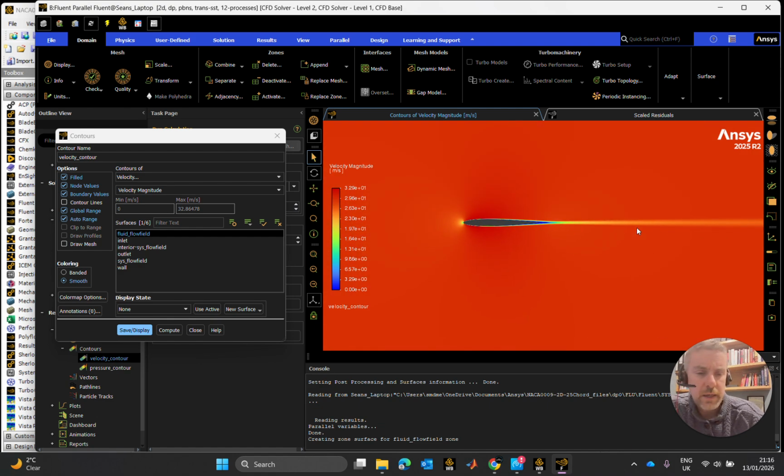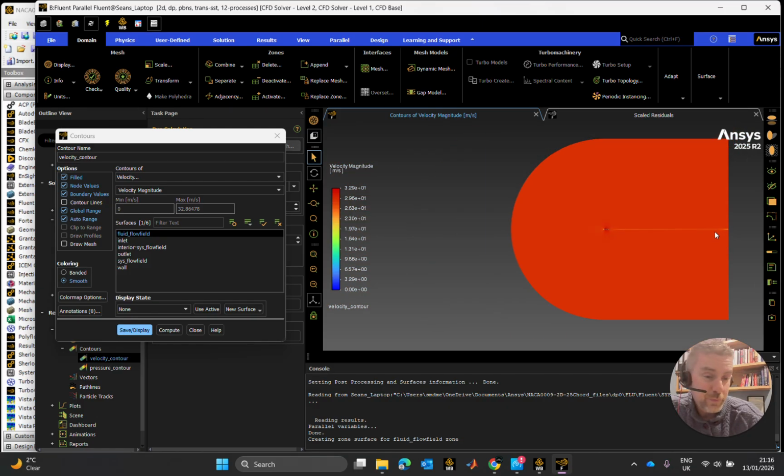So with all that said, we can also see here very interestingly, why did you make that 20 chord lengths out to the back? We'll have a look. Not so much the wake, I wouldn't even call it a wake that far back, but certainly a slipstream coming off of that. It reaches very far back, 29 meters a second.